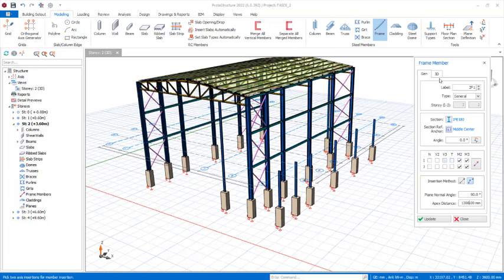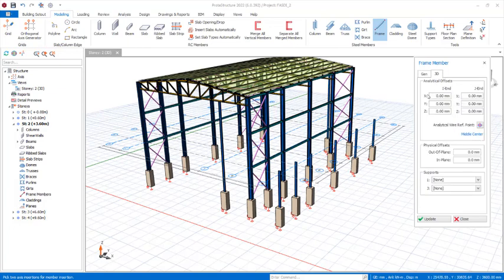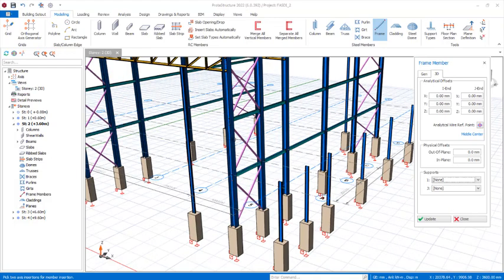All right, if you come to the 3D sections, in these sections you can see the analytical offset. If you want to offset the analytical line, you can use these provisions. For the sake of this lesson, we are not going to do that. And then if you come over here, you have a support. If maybe you want the beam to have a support, you can select your support here. In the last lesson, we were able to create a pin support and a default fixed support for the foundations. But for this we wouldn't have any support, so we want to place it right away.